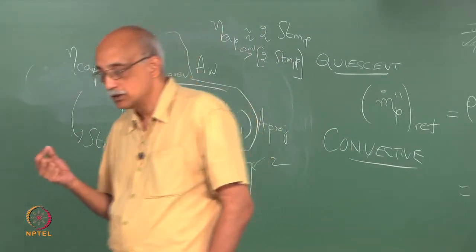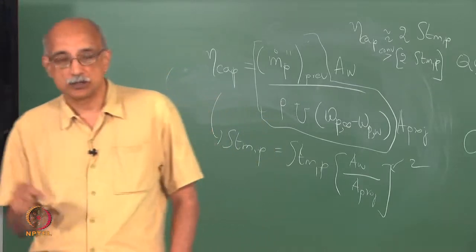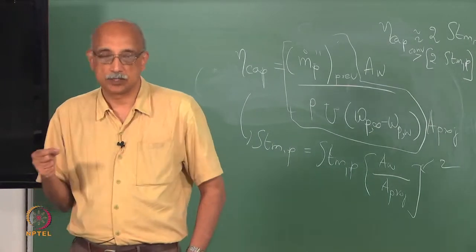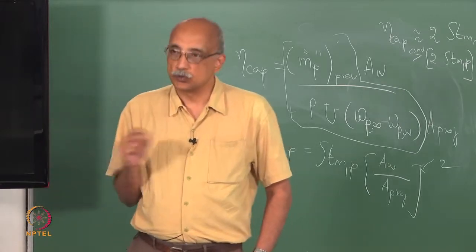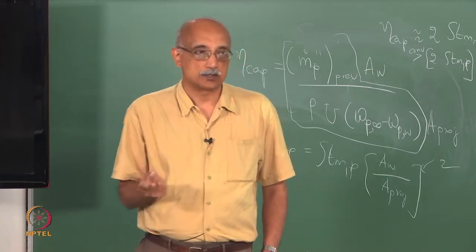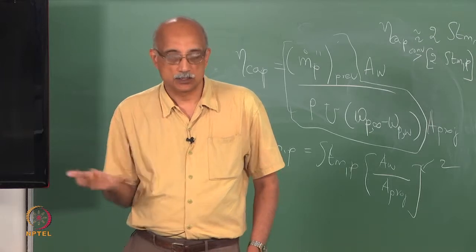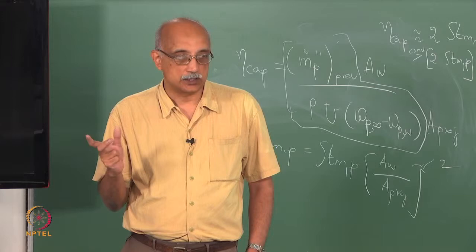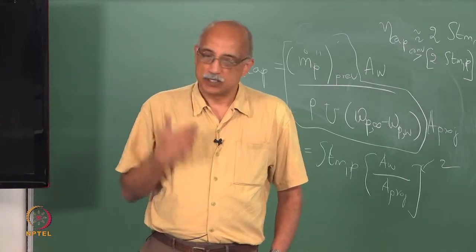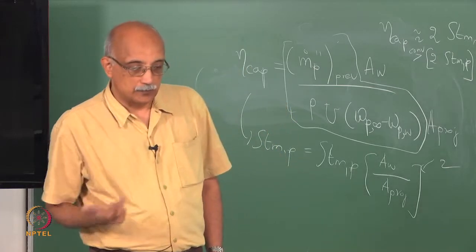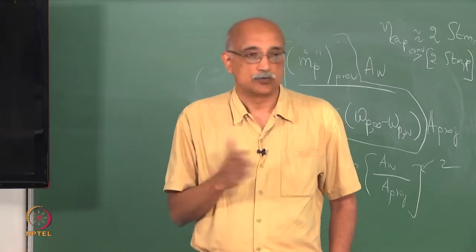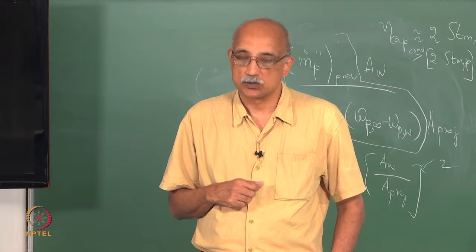So, we studied the various mechanisms of particle to surface adhesion and the various forces involved in particle to particle cohesion. So, in terms of particle to surface adhesion, we discussed initially the van der Waals forces and the Hamaker constant that describes these forces, various forms of electrostatic forces, surface tension forces, hydrophobic, hydrophilic forces and so on.